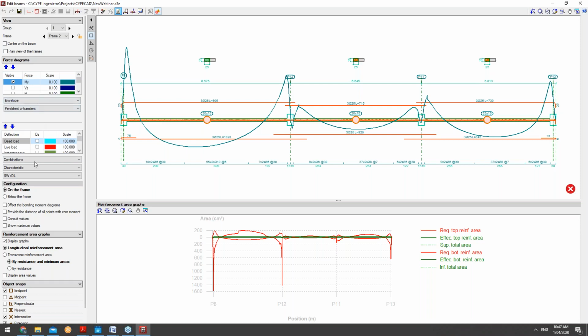Of course, you can see I have some specifications that I'm able to do. I can view my moment, my vertical and horizontal forces inside the editing of this beam as well. Also looking at the different combinations and envelope load specifications that I've set. I can view bending moment diagrams inside the program as well. I can also look at the addition of reinforcements, so I can introduce assembly reinforcements, additional reinforcements, and skin reinforcements into the structure here.